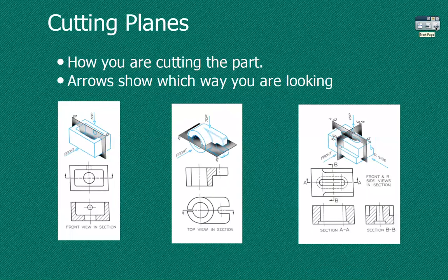All right. In order to get a section, we have to put in our cutting plane line. That's telling it where we're cutting. So in Inventor, that's what we draw: the cutting plane line. Then it makes the cut based on that. The view where we cut needs to be on the opposite side of where the arrows are pointing. Inventor's going to do that automatically.